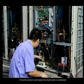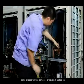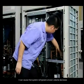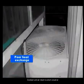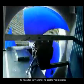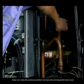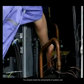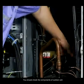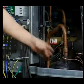2. The outdoor unit may have a malfunction or protection. Some bypass valves are damaged or stuck and so on. It can cause the system refrigerant circulation volume to decrease. The outdoor unit air return is short circuited or the installation environment is not good for heat exchange. Outdoor fan air volume is small. These can make the working condition very bad and running performance bad. You should check the components of the outdoor unit and judge if their action is normal when the system is running.